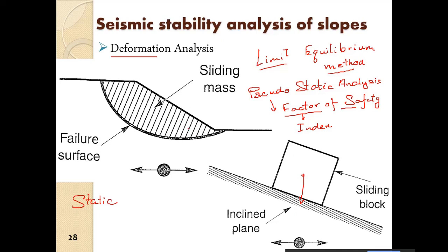And if there is dynamic force, we assume there is an acceleration in the horizontal direction. That is the dynamic inertial force that we assume will occur on the soil due to an earthquake. And of course, we divide that total destabilizing force or moment by the available resisting forces, or the soil resistance. We have also seen that the limit equilibrium method cannot take into account the variation in the soil resistance due to various earthquake loading.